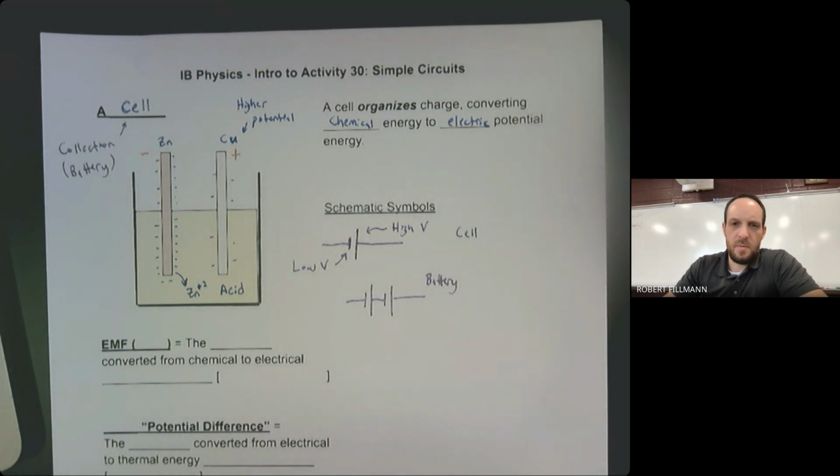You even do this if you put batteries in a flashlight. Say AAs are 1.5 volts. If you put two AAs in a flashlight, you get 3 volts. They have a combined effect. Car batteries, for instance, consist of, I believe, six 2-volt cells. So you get a total of 12 volts for a car battery.